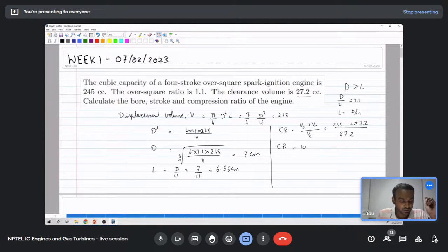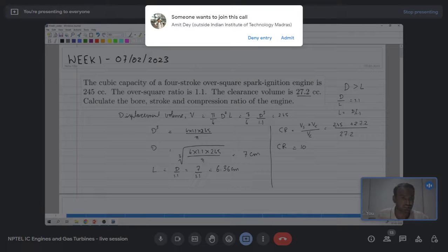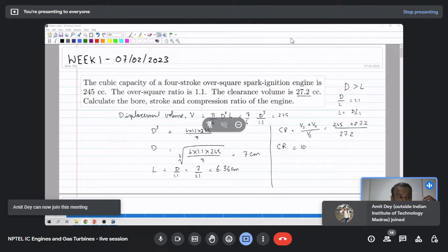Fine, anyway. Since diesel engines have a higher compression ratio, the in-cylinder pressures are very high, and the rate of pressure rise is also very high in a diesel engine. This rate of pressure rise corresponds directly to the combustion noise.